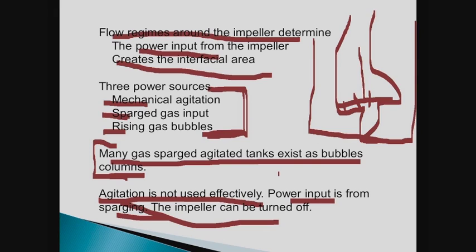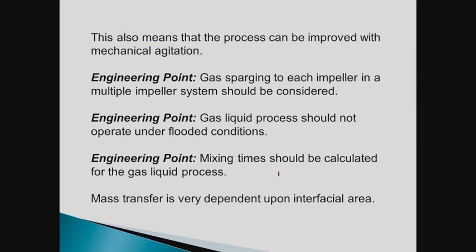The reason the 18 hours was important was that the seals had a tendency to leak, so there was more leakage from the seals at 18 hours. And it was dangerous stuff, apparently. Anyway, from what I could tell, the impeller could be turned off after half an hour, and they weren't getting very much performance from the agitator.